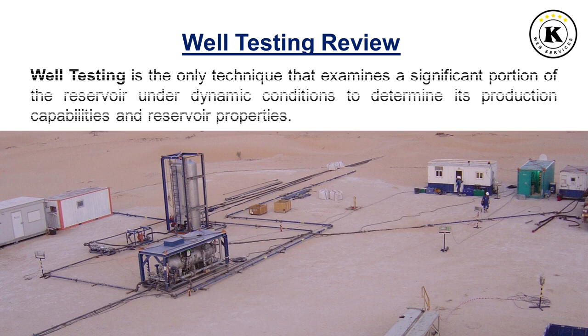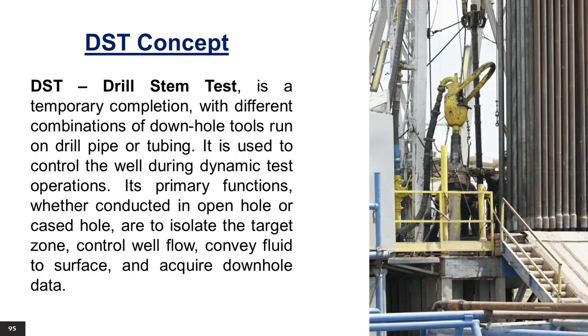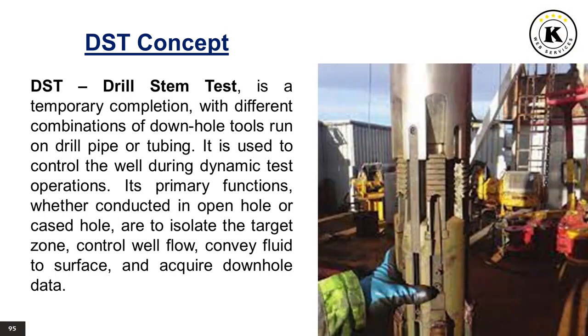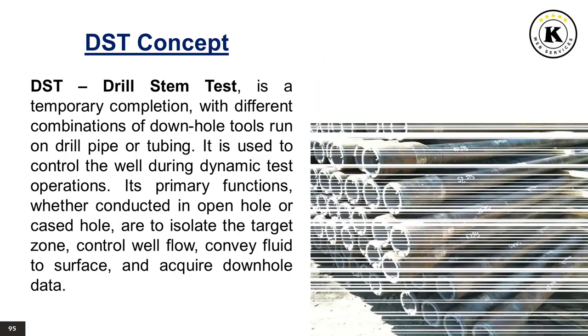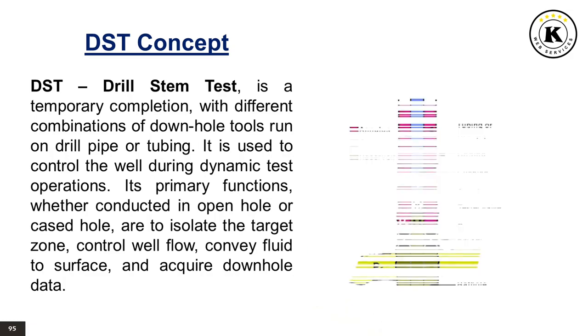Well testing review. Well testing is the only technique that examines a significant portion of the reservoir under dynamic conditions to determine its production capabilities and reservoir properties. DST concept. DST, drill stem test, is a temporary completion with different combinations of downhole tools run on drill pipe or tubing. It is used to control the well during dynamic test operations.